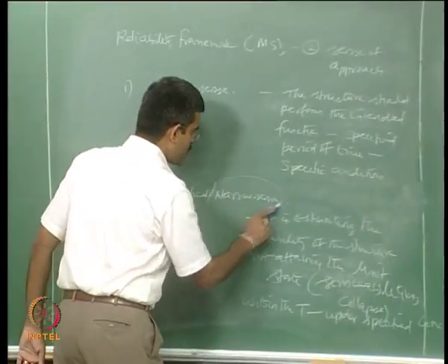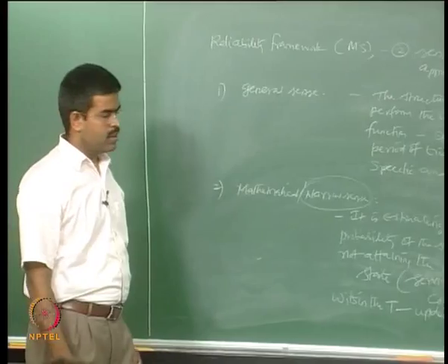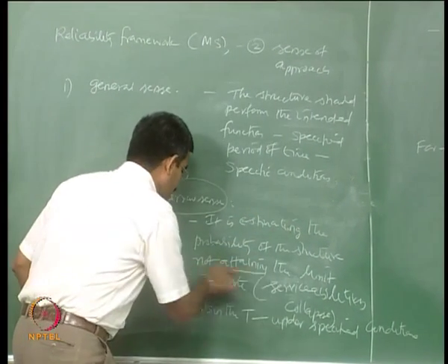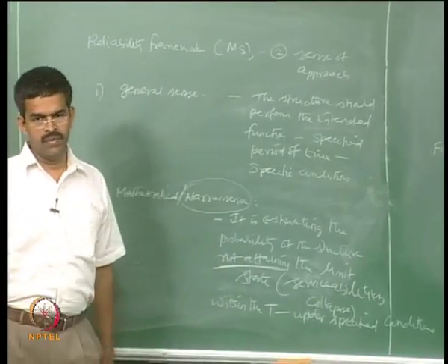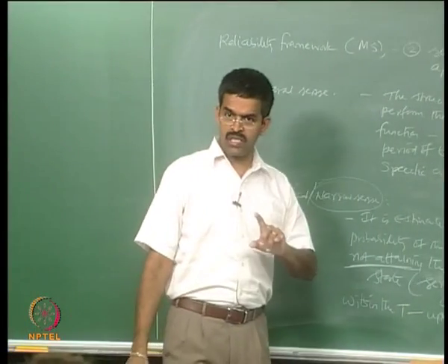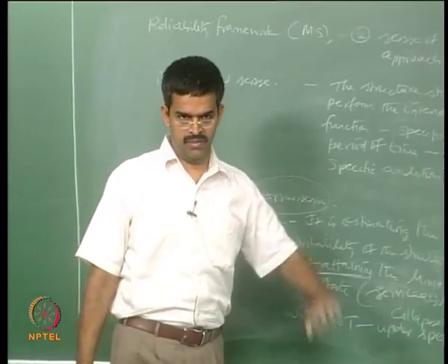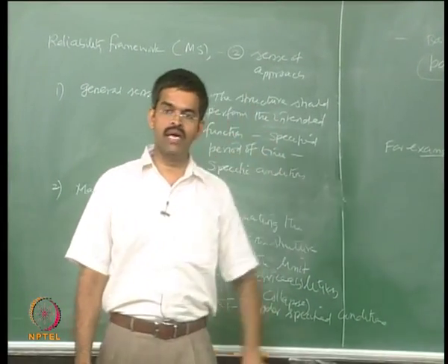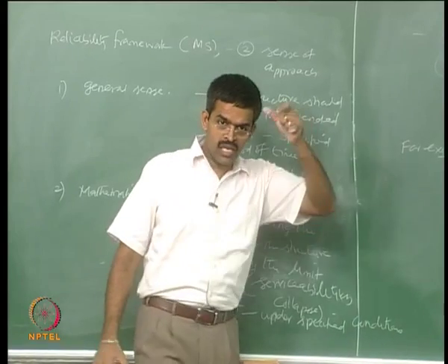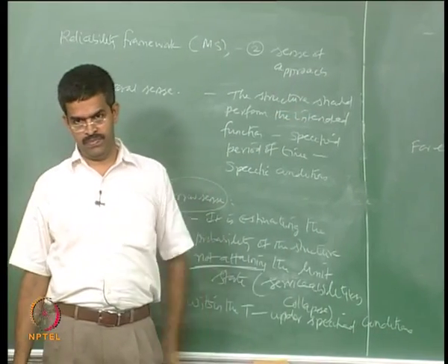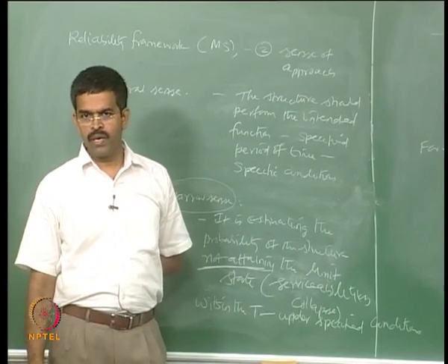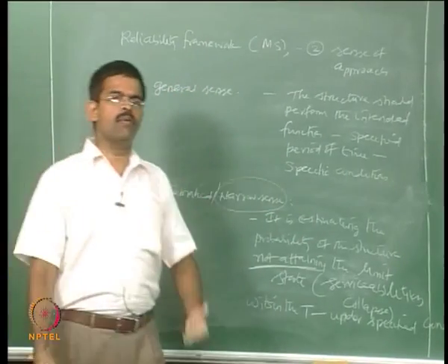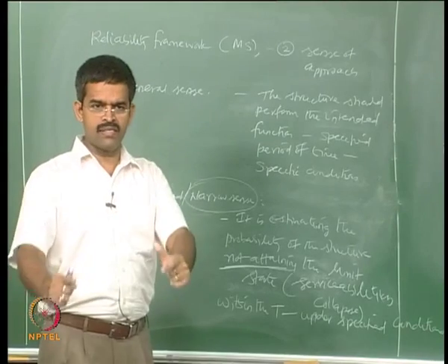In the narrow sense, it says that try to estimate the probability that the structure will not attain the limit state, though the structure is designed to attain a limit state. Very important. Plastic analysis and design is a methodology where the structure should reach the limit state, what we call a collapse load. So, here reliability is what is the probability the structure will not attain that state.